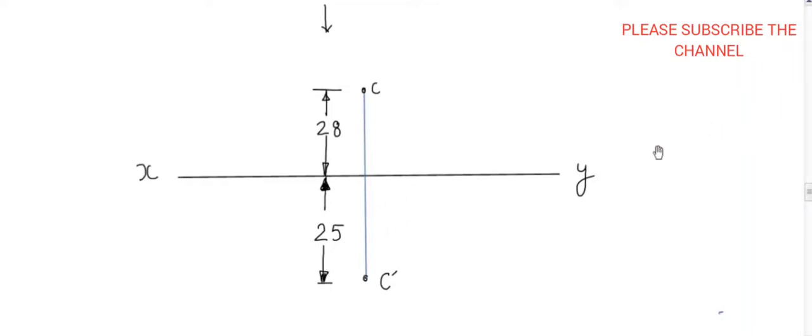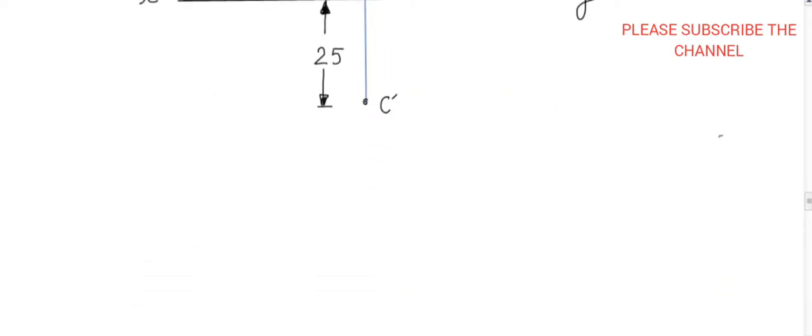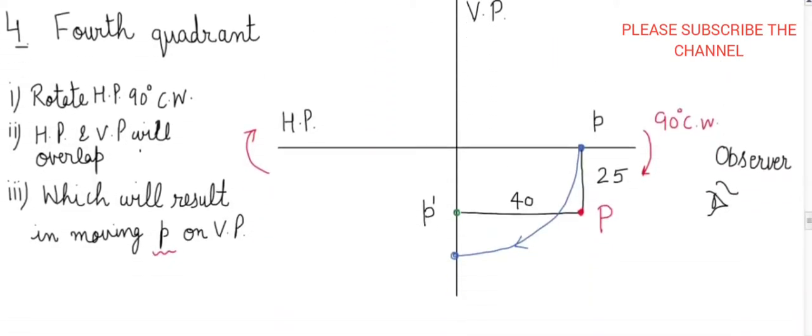Remember that in the second quadrant and in the third quadrant, the principal plane of projection, which is VP, needs to be transparent. HP is also a principal plane of projection, but I'm talking about the vertical plane. The vertical plane needs to be transparent. This is the most important question which is asked in competitive exams also. So now move to the fourth quadrant.